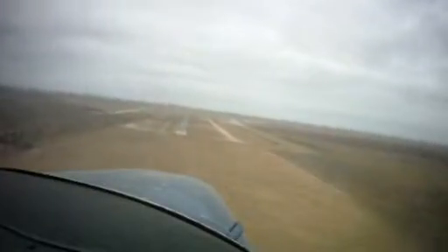Now I'm going to anticipate my turn because the wind is pushing me in this direction, so I have a very strong headwind, so the plane is going to float a lot. It's going to be hanging there in the air, so I need to remove, as you know right now, my power all the way to idle to allow the plane to descend. Now this is the important thing over here.